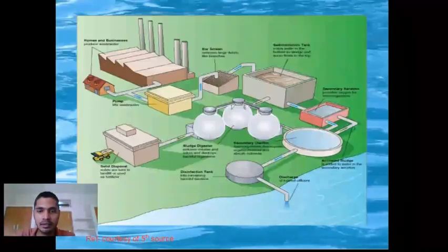An effluent treatment plant can be divided into three separate units: primary treatment, secondary treatment, and tertiary treatment. The primary treatment consists of bar screens or any other physical sedimentation units, where the big particles such as clothes, paper, or any other suspended solids and plastics are separated out.